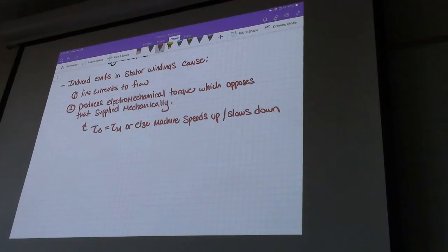So you can have small changes. Normally, the well of stability is small. We're not going to have the frequency go from 60 hertz to 100 hertz and then eventually return to 60. But to accommodate changes in load, it may go from 60 to 60.2 or 60.3, reach the new equilibrium value, and then return back to 60.